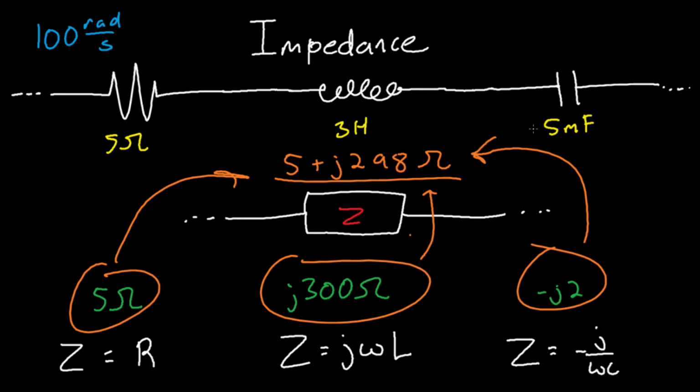And this complex number is actually the impedance of your impedance box, okay? After combining all together, you can still use Ohm's law. So V bar is equal to I times Z. I'm going to put a bar on top to clarify that this is a complex number, or a phasor, or a polar coordinate in the phasor domain.